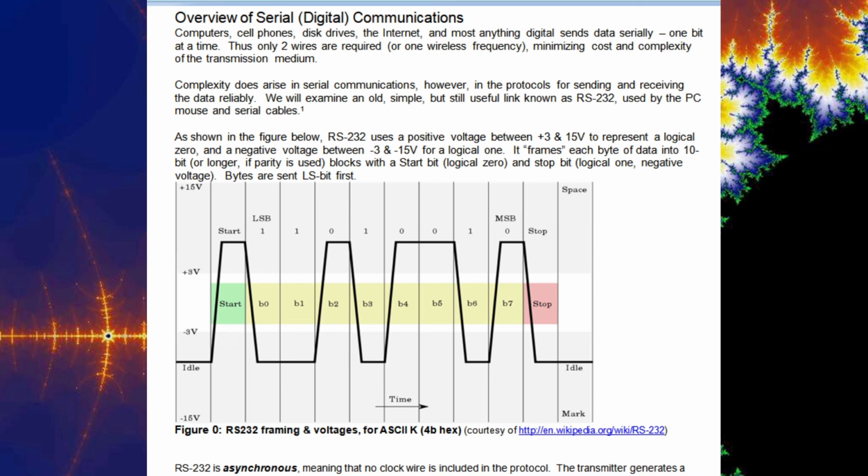Again, if I type in the binary here, that would be 0100, that's for the 4, and then the B is 1011. So you can see here, if you read this left to right, then it's going to look like it's backwards. But the reason it's doing that is because it sends the least significant bit first over the data transmission. And again, you're typically parallel loading in on the shift register on the transmission side, and then you send it serially out.